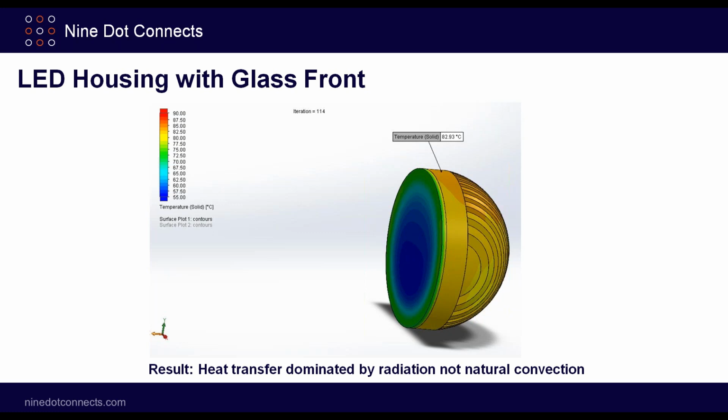Now, that came from the electrical side. I knew how much thermal dissipation was coming from the circuit board. And in front, you're seeing this is actually glass that's heating up. I'm looking at the temperature of the glass. So I now know I've got a touch temperature which is well beyond the safety limit.